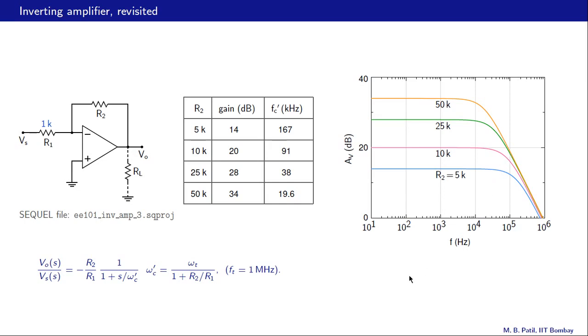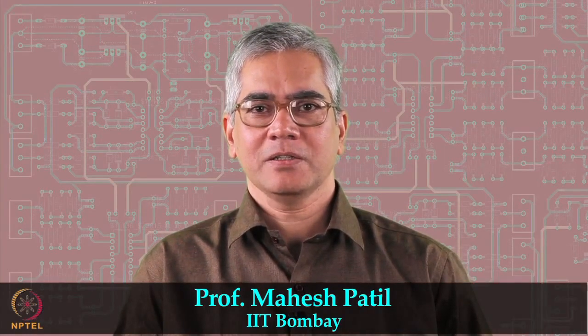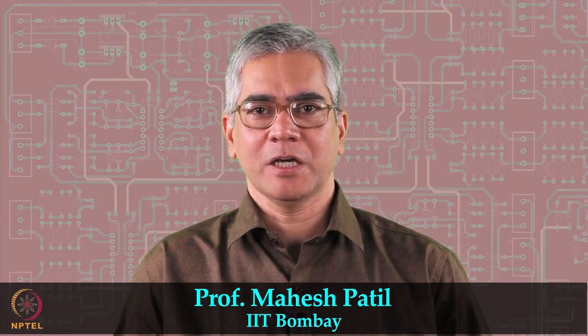And the important message to take home from here is that there is a trade-off between gain and bandwidth. We cannot have high gain as well as high corner frequency at the same time. To summarize, we have looked at amplitude control in sinusoidal oscillators using a gain limiting network. We then looked at the frequency response of an inverting amplifier and explained why the gain drops at high frequencies.